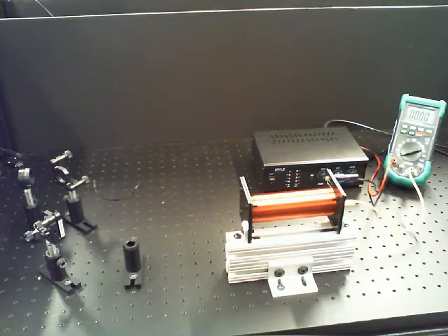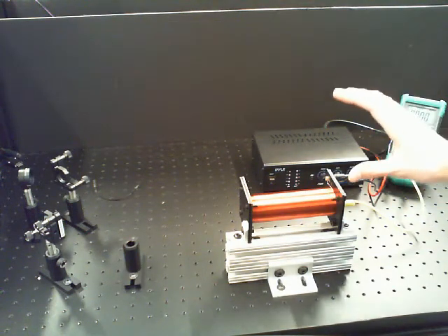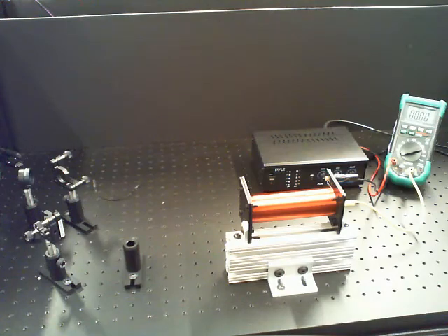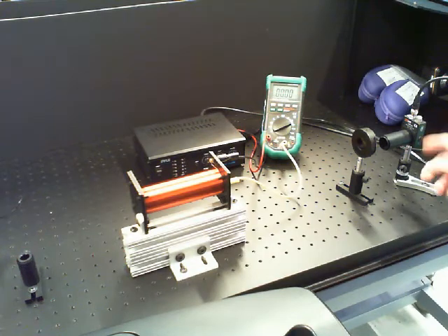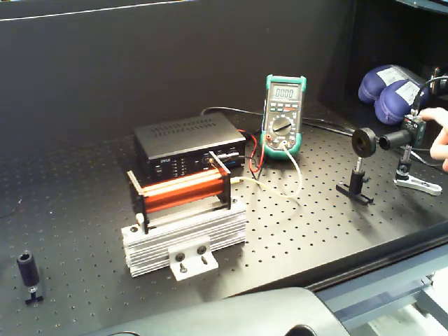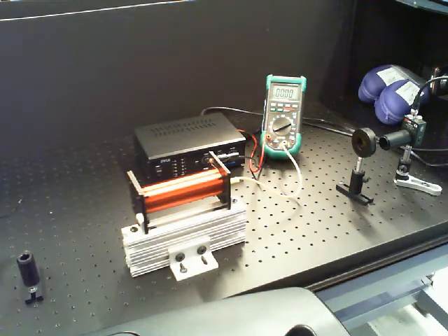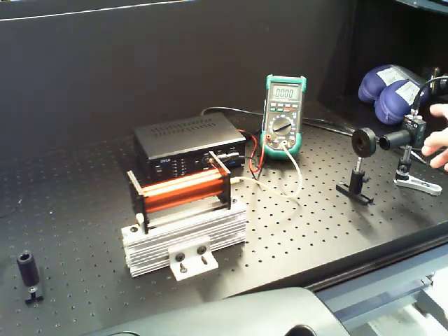And rather than just increasing the DC current in here and looking at this change in rotation, what we're going to do is have a time-varying current in here. Now, the purpose of that is so that the signal that you receive will also be a time-varying signal. But you'll know something about the properties of the time-varying signal on this photodetector. It will be varying at the same rate at which your function generator is set. So if you set the function generator to 45 hertz, then the signal on your detector will be at 45 hertz.